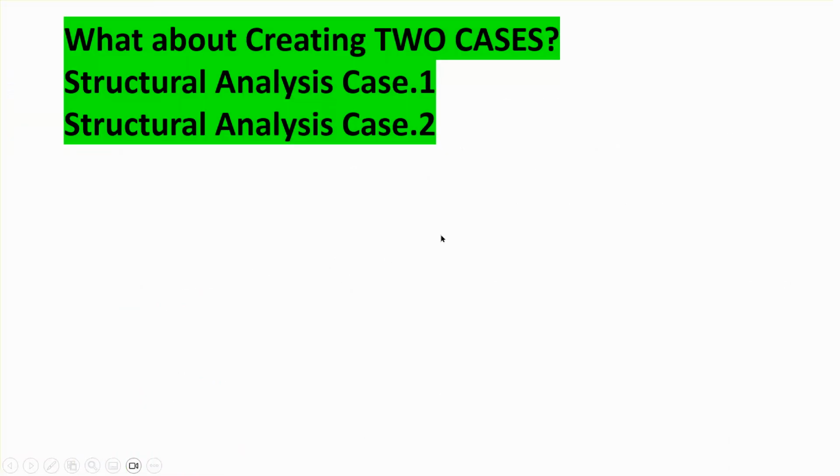What is this business of one single structural analysis case? You may or may not have noticed that when you go into structural scenario creation, it immediately creates a structural analysis case. And unless you have to, you just stay there, applying the loads and displacements.